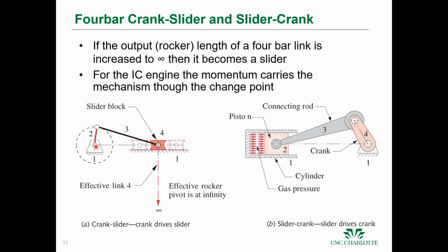Okay, so this is the working principle of an internal combustion engine. So you need to have a motor input to keep it going through the collinear points. Okay, but often we will put a driver here. For the internal combustion engine, it's not a crank slider, but a slider crank because the slider drives the crank. Again, we have the same situation where the 4th bar here goes off to infinity, but the internal combustion from the engine causes it to rotate, and then the inertia from the engine keeps it coming back around to compress the gas and repeat the cycle. But it's kind of interesting to think about this internal combustion engine as a 4-bar mechanism.